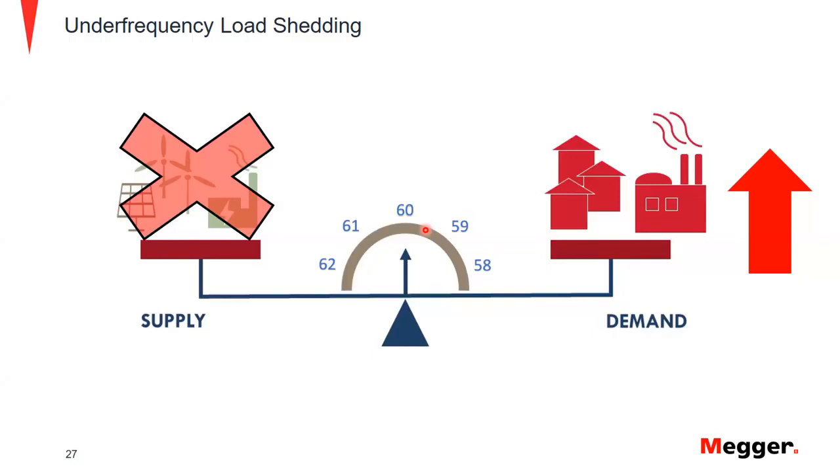We open the connecting breaker out in the substation. It connects us to the grid. We become unsynchronized to the grid. And then now our generator breaker is opening, and we have to get everything back up to where it was. But even at that point, we can't do that because we still have to shed some of the demand. We need to make this demand smaller.